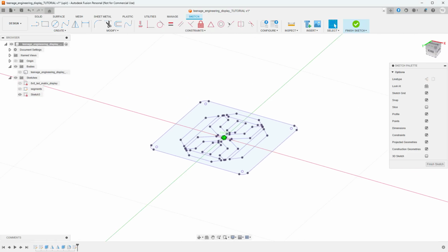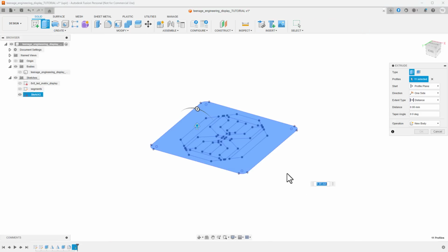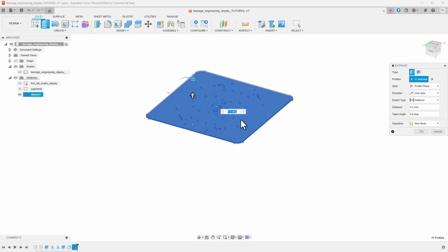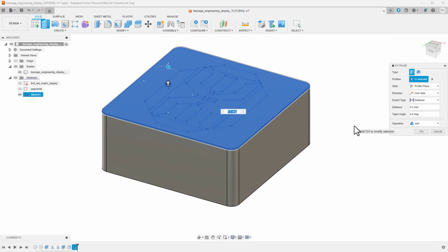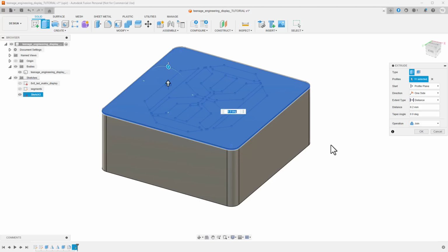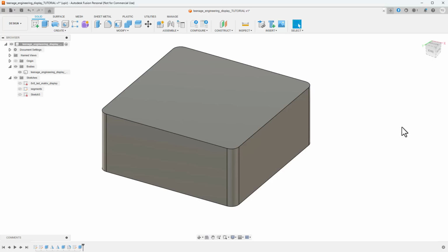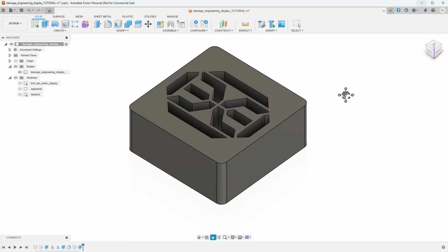So we can just finish the sketch and then select the extrude command and extrude everything by one layer, which in our case is 0.2 mm. But before we click the OK button, let's also show the rest of the 3D body. And if we do that, it should change the operation to join, so it will join this diffuser layer with the main 3D object. So click the OK button, and we now have the 3D body where the first layer is actually flat, that's the diffuse layer.